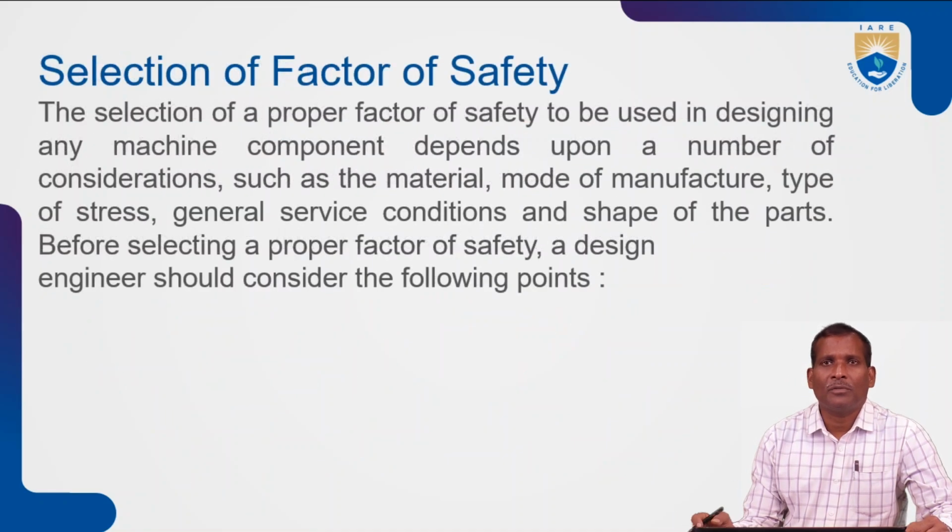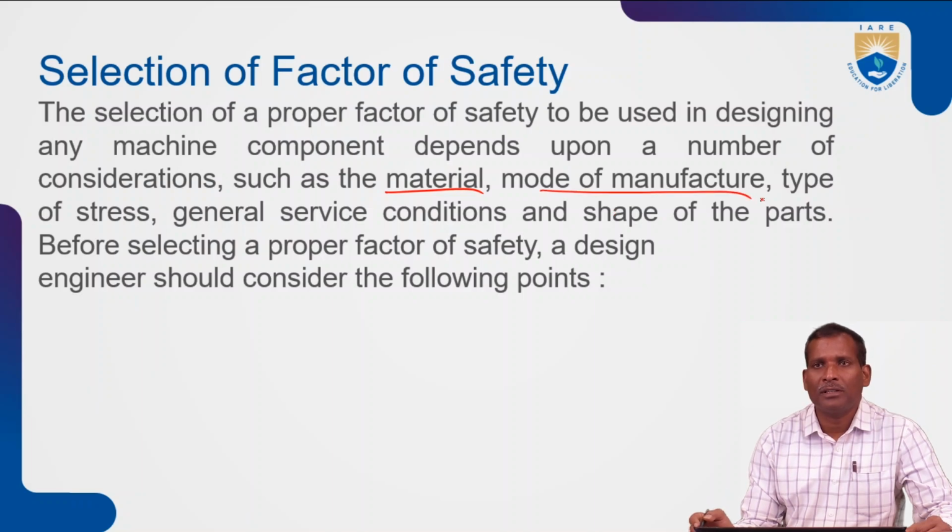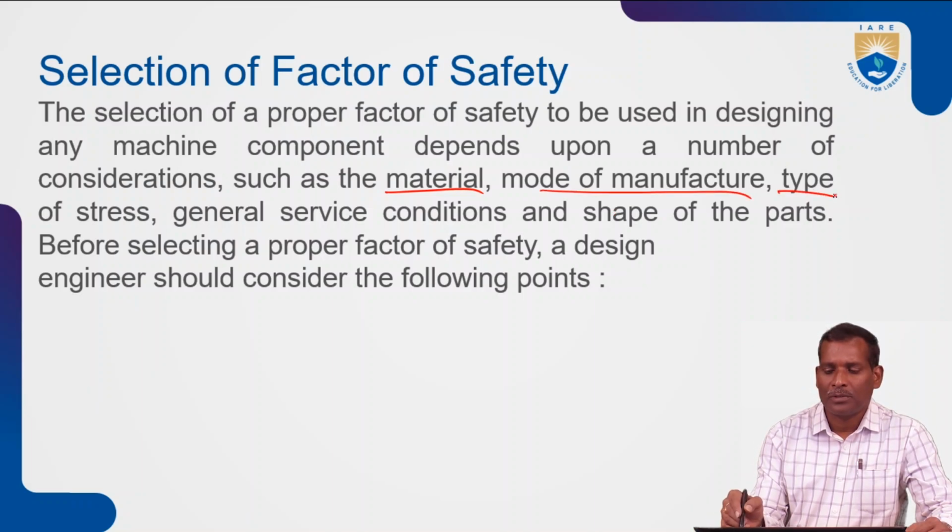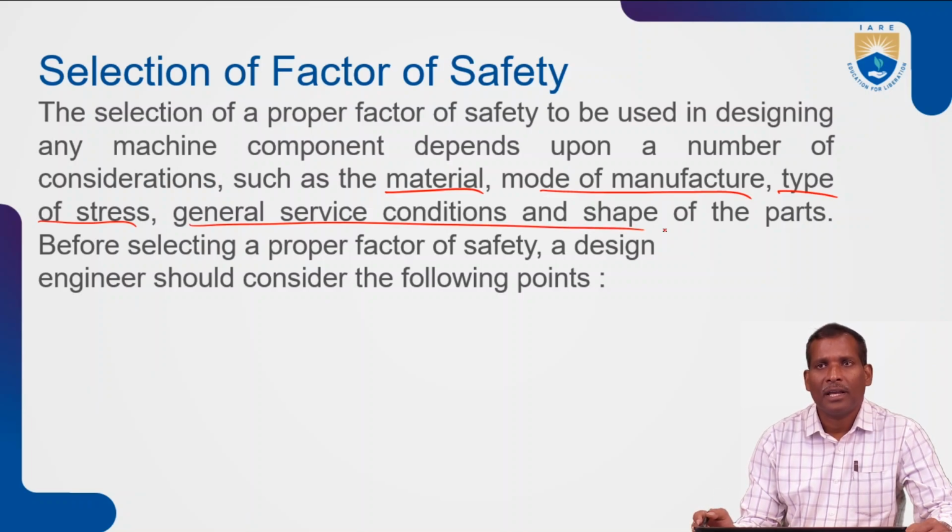So how do you select the factor of safety? The selection of a proper factor of safety to be used in designing any machine component depends upon a number of considerations, such as the material and the mode of manufacture, type of stress, general service conditions, and the shape of the parts.